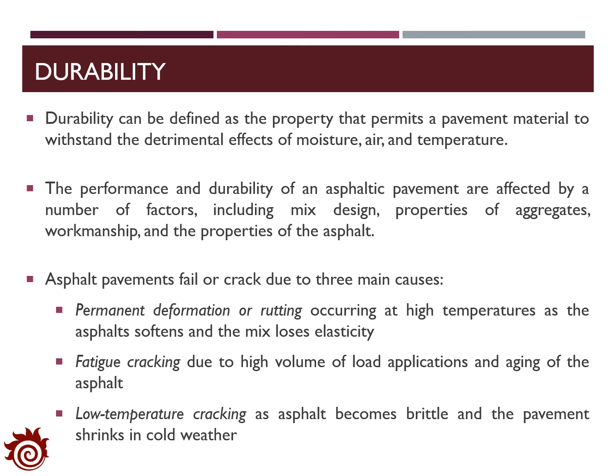The second cause is fatigue cracking due to the high volume of loading applied on the road and the aging of the asphalt. And the last one is low temperature cracking. When the temperature is low, the asphalt becomes brittle and the pavement shrinks in cold weather. The asphalt cement should be designed and mixed with appropriate aggregates to overcome these three potential causes.